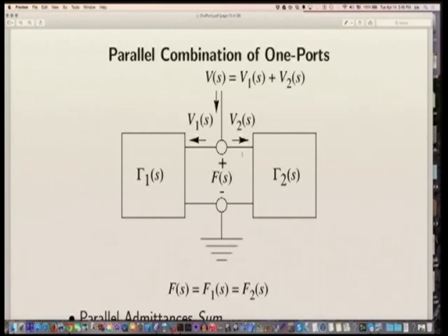So the plan is, we're talking about just normal circuit theory where you say that the speed of light is infinite, the speed of sound is infinite. Another way of saying it is the wavelengths are very large. The wavelengths are much larger than the circuit dimensions. And so we don't have to deal with traveling wave notions at all. Everything's just scalar voltages and currents. And so we avoid all that. And that's what normal circuits do.